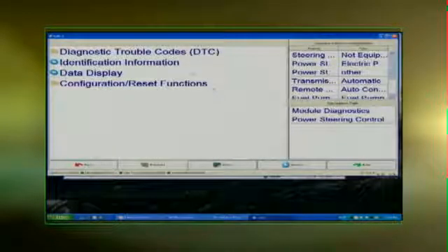We'll check codes first off. They have the ability to do self-diagnostics with electric power steering. That would be a must. You can imagine if you have regular hydraulic steering, and we talked about this in the program, if you don't get that spool valve, that centering valve in the rack or in the steering gearbox just right, you can start the engine, and as that pumps up power steering, it can move the steering wheel all by itself.